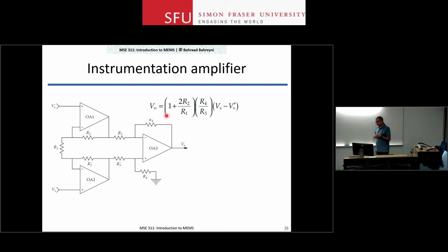You can do that. There are op-amp packages that have 4 op-amps in them. So you can easily make this with one package on your PCB. Or you may choose to buy an instrumentation amplifier. So these are devices that look like an op-amp from outside, same 8-pin package or things like that. But it's that circuit inside that package, the circuit on the left inside this package. What they do here is that they provide two terminals, in most cases, not always. Sometimes the gain is fixed. But they provide two terminals for you to set the gain.